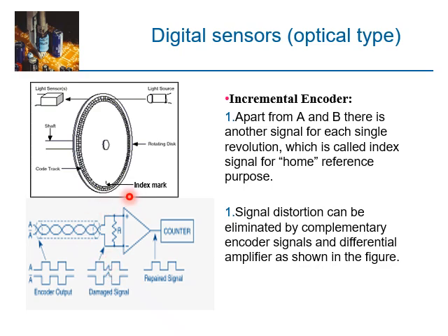When you have something called common mode noise, it can be easily rectified by an amplifier circuit or an op-amp circuit, and you can have a nice flawless signal here, as you can see. We can use a subtraction circuit for this purpose, which we will be discussing later in our course. This is why each channel A, B, C will have its counterpart A bar, B bar, C bar for overcoming the common mode noise.